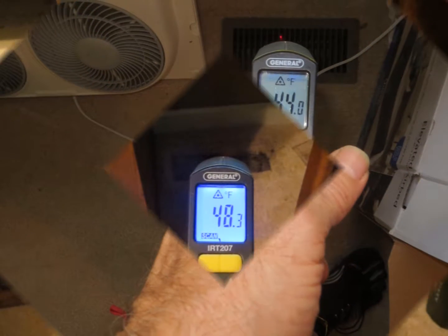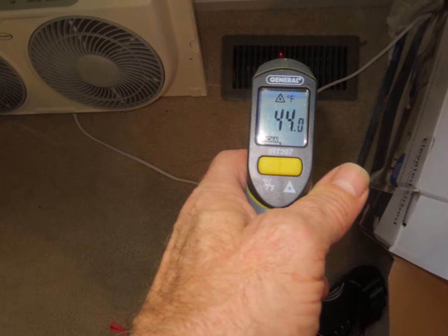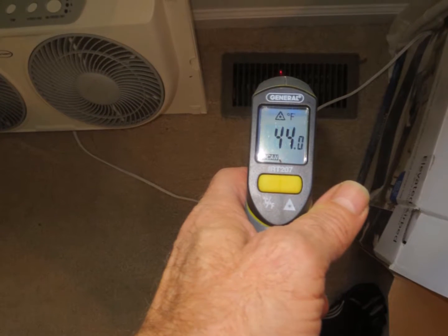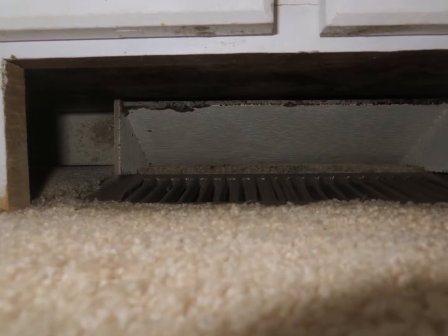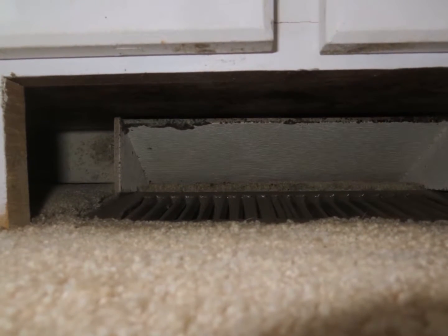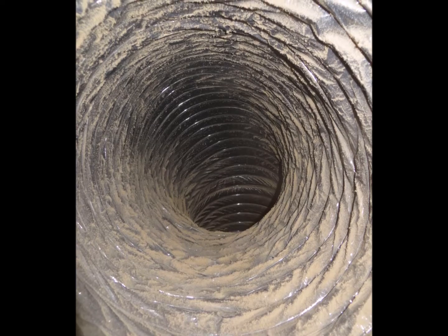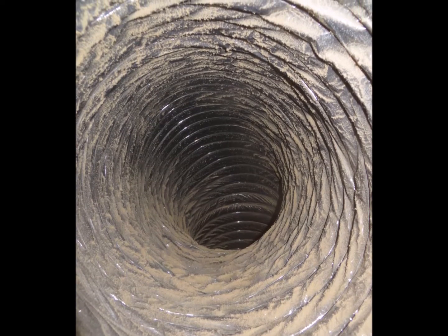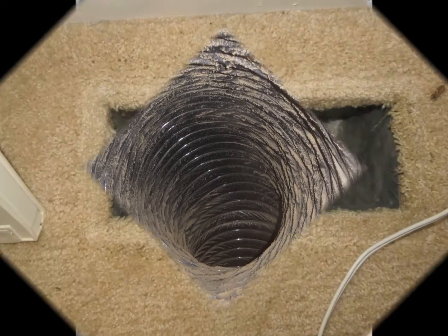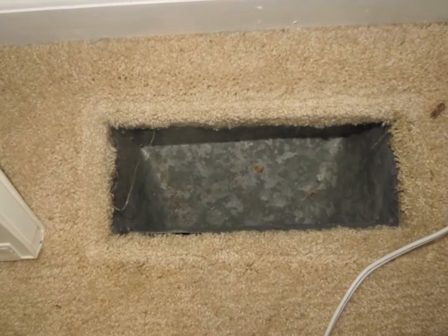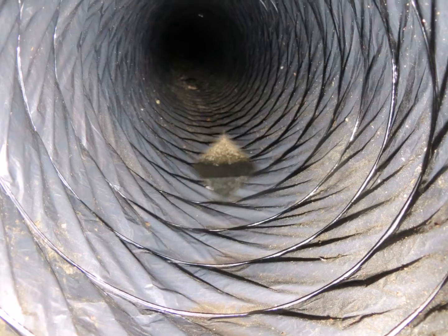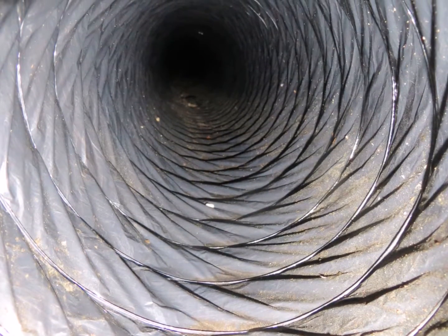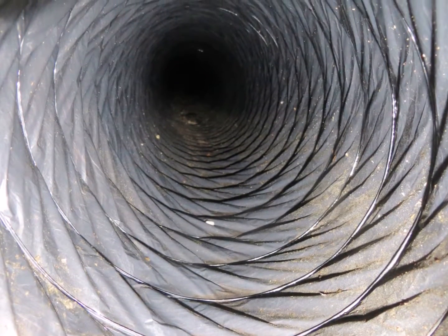The air coming out of the ducts when the AC is on is very cold. This may be an indication that the system short cycles, which would create high levels of humidity and cause mold to grow. The return side shows a lot of debris in the ducts. Other boots upstairs are not corroded at all, and again, the air ducts are not full of rust.